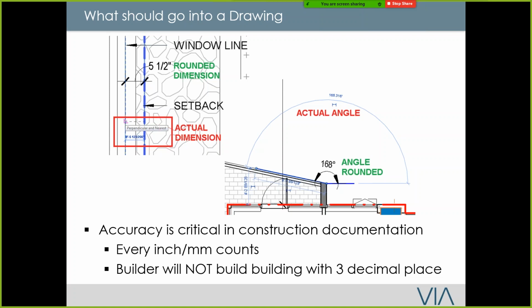Okay, Revit wants to be a whole number. It doesn't like to have this fraction number that's really weird. And same with angles as well. Just keep it happy. Now, there's one glitch that Revit does: if you have a 45-degree angle, sometimes Revit would tell you, oh, this is not aligned, even though it's 45-degree. Just keep in mind, Revit will do that.